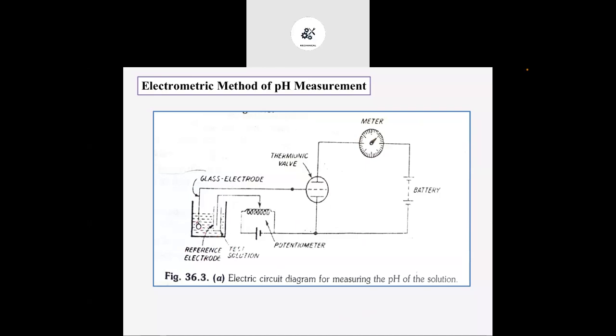You will see there is a reference electrode, and the test solution, which is inside this beaker. Then this one is the glass electrode. It is connected to this thermionic valve, and the reference electrode is connected to the potentiometer. Okay, this one is the potentiometer. This particular meter will indicate the pH value directly, and it is connected to the battery because we require some voltage.